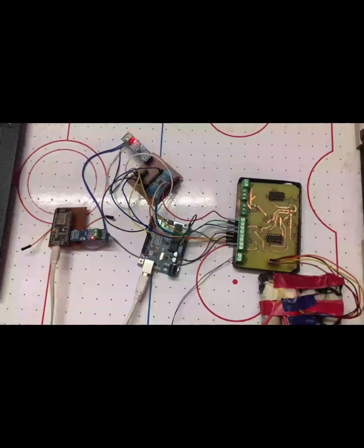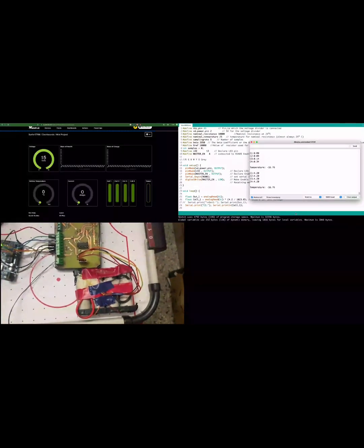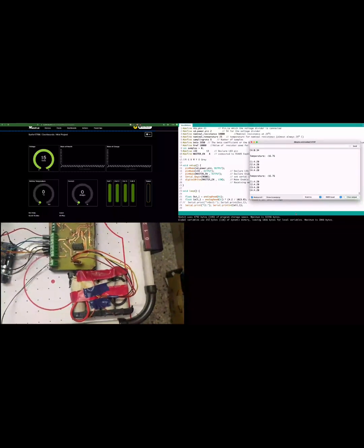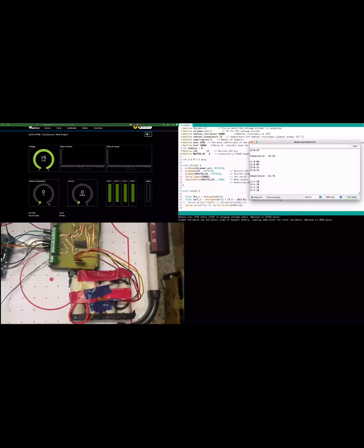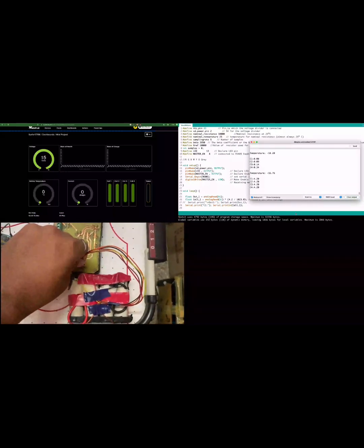So here, step 1, we are going to be showing the actual reading values from the battery. As you can see on your screens, the battery performance monitor is reading 4.2 volts, and correspondingly on the Adafruit dashboard you can see that the cell voltages are all being correctly reflected. But let's say, for example, our battery values are coming 0, so let me remove this a little bit.